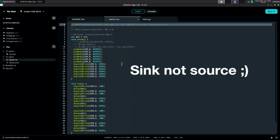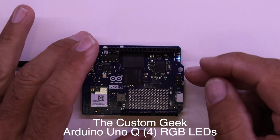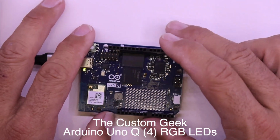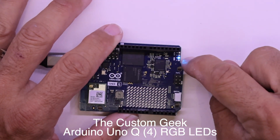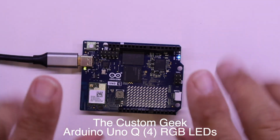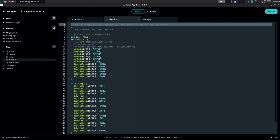So if we go back into the Sketch, one thing to note is that the outputs are reversed. So low is high and high is low. So if you digital write high, that turns the LED off. If you digital write low, that turns it on. And without bit banging anything or going into direct port manipulation, these are controlled without PWM. So it's just high and low. There's no dimming yet.